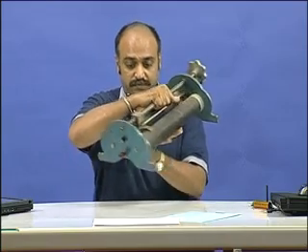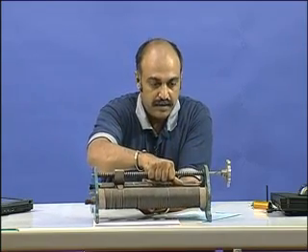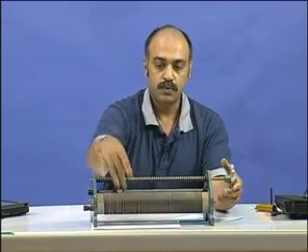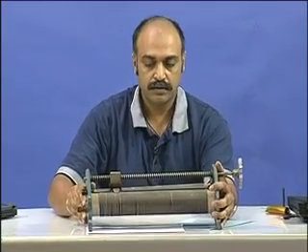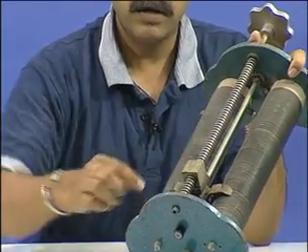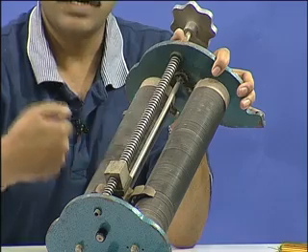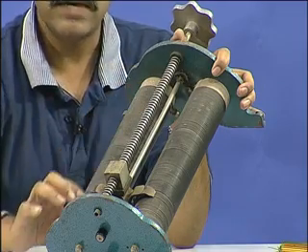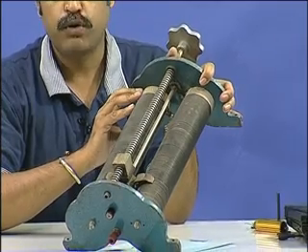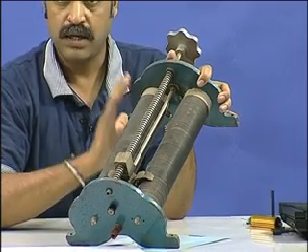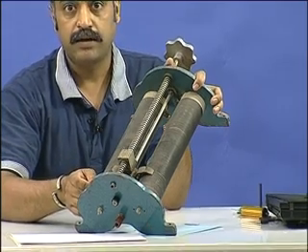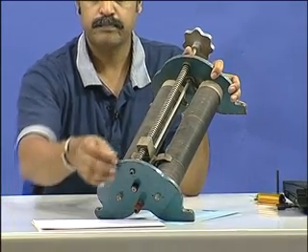It is pretty heavy. Okay, so let me place it here. You see that there are 2 cylinders. Are you able to see? I will hold it like that. There are 2 cylinders composed of wire wound wires. This gives the resistance, and they are connected in parallel such that they can handle higher current and therefore more dissipation. This can handle something like 25 amps and they are 2 ohms, which means something like 1250 watts.